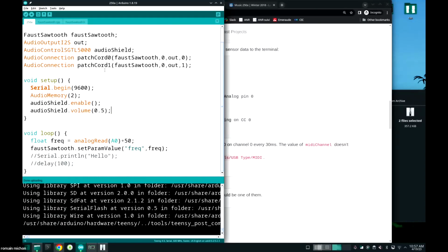Okay, so the FSR is working in a very similar way than many other sensors. For example, the photoresistor that you had in your kit, which measures the amount of light in the room, works exactly the same way as the FSR, and many sensors work this way. They only have 2 pins, and in that case, you want to use a circuit which looks like this. So, for example, here, if I remove the FSR and if I plug the photoresistor instead, it should still...